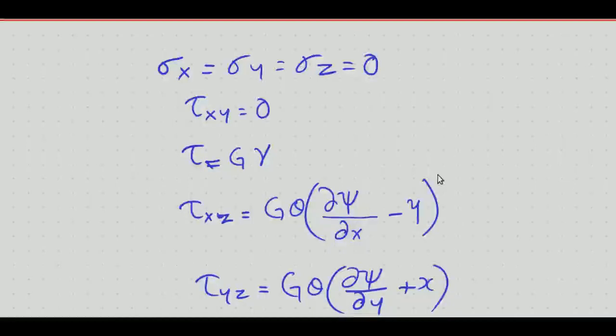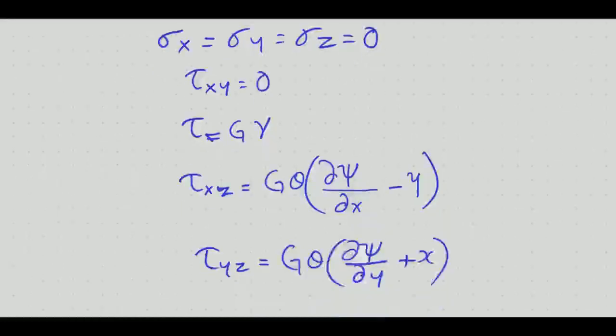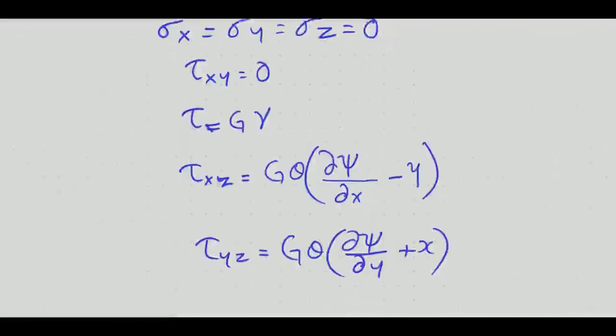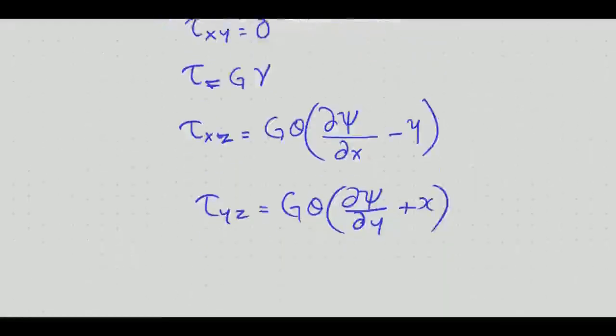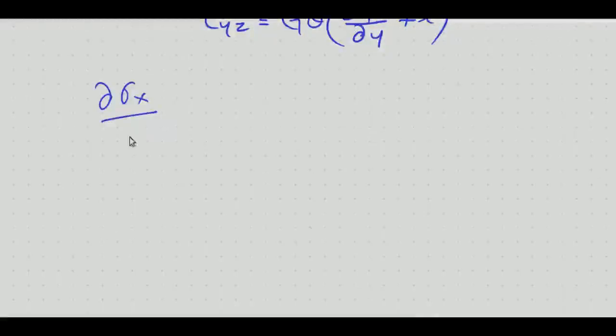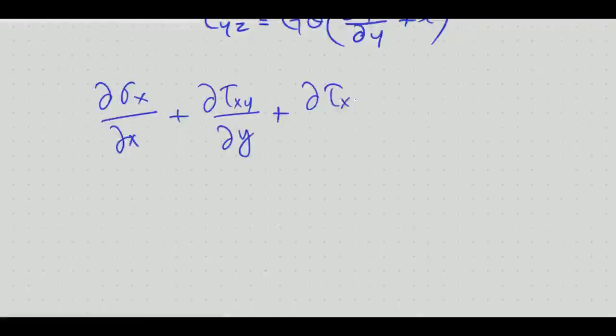These stress components must satisfy the differential equations of equilibrium. So now we are going to write the differential equations. We have three differential equations of equilibrium, that is ∂σx/∂x plus ∂τxy/∂y plus ∂τxz/∂z equal to 0.